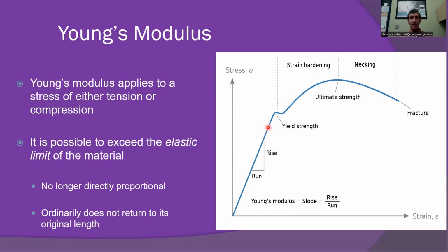Now, obviously, with a lot of cycling, if we create tension, then we release tension, we create tension, defects in the material can create fractures. But for a uniform material, we would imagine that once the stress is relieved, the strain will be reduced to zero. It will take its original shape.